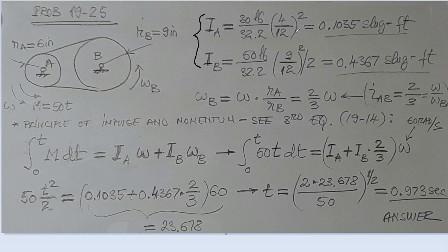Why put 4 here? Let me pause. Sorry, there was no mistake. So this 4 inches is the radius of gyration. We're not going to use the radius of the flywheel, it's the radius of gyration. There is some mass redistribution. This is not a perfect disc. Probably has a web and a thicker rim.